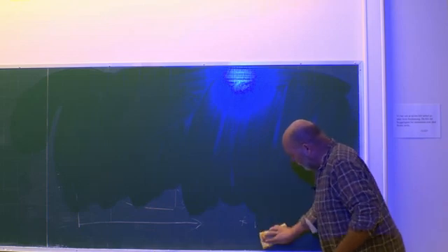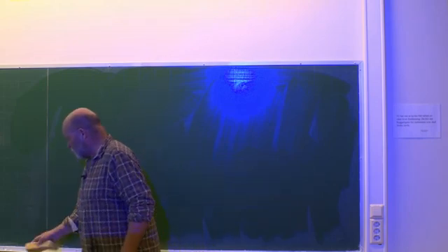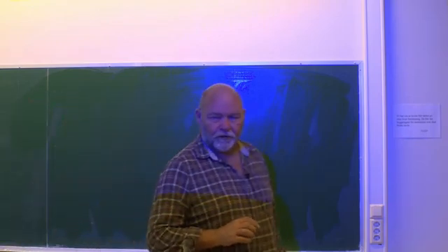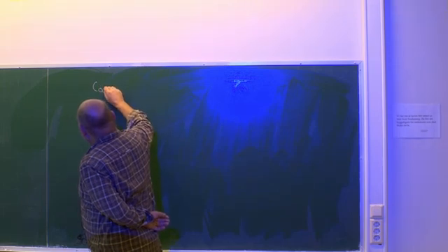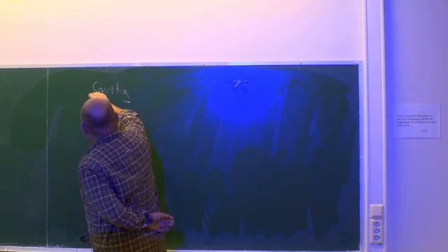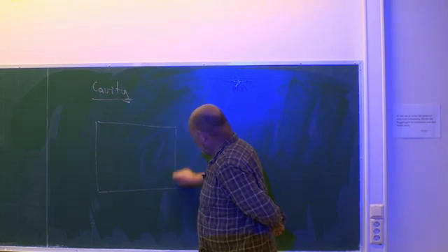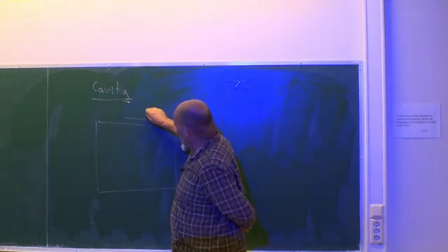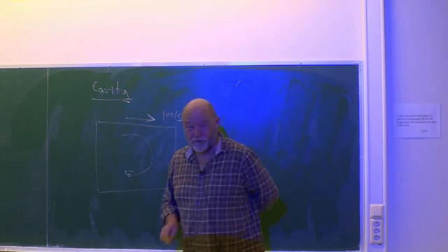Now, programming in OpenFOAM, changing the source codes, creating your own version of some programs, a little C++ programming, piece of cake. Now let's have a look at some scenarios. I'm going to use the classical cavity case, a square box. This is moving with a velocity of 1 meter per second, and we have a nice big vortex.